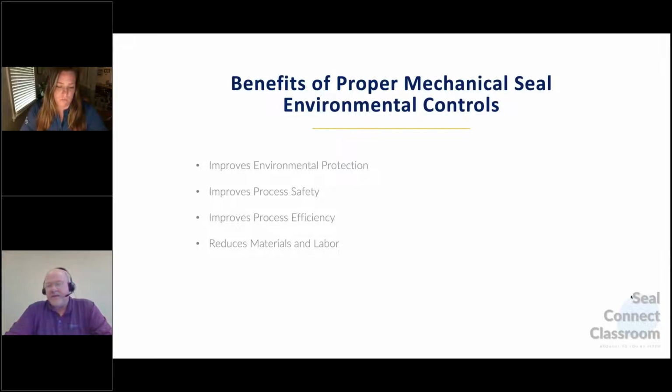The other thing becomes financial issues. Apply the correct environmental controls to create the correct environment for the seal to run in, not just the external environment. We're talking about the internal environment for the seal to run in, to improve process efficiency. We're talking about reducing product contamination from the fluids that you use to create the environment for the seal to run in.